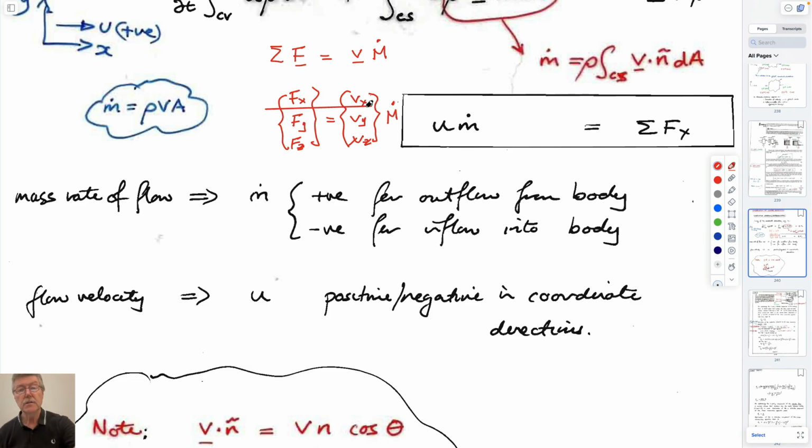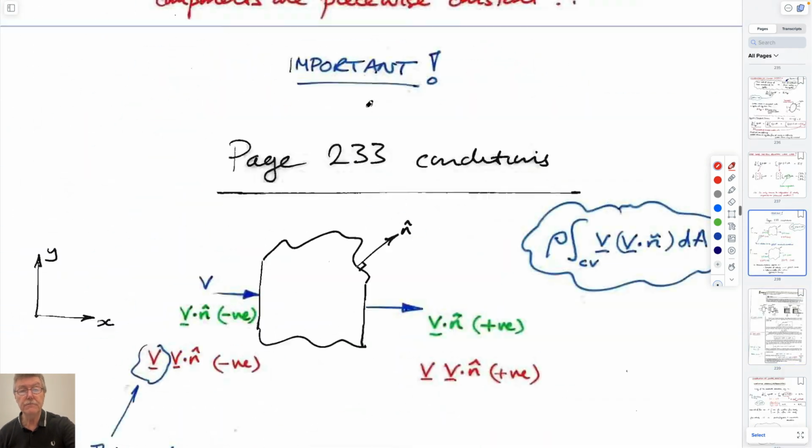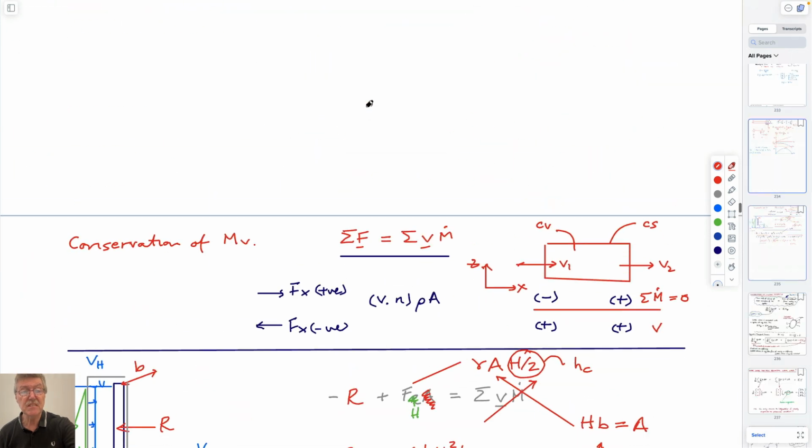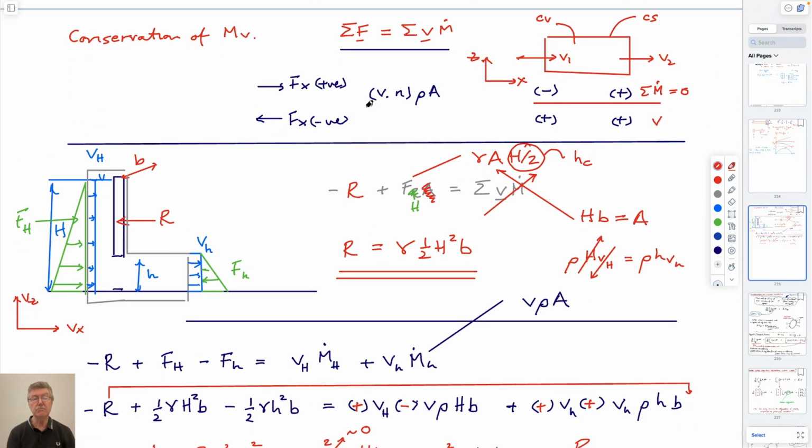We only need one equation. We could also solve for forces vertically if we wanted to. I'm not sure what it would tell us, but we could do it in z, and we could do it in x. I think the sum of the forces in both z and x would be zero. No net forces, because if you took a box, this L-shaped box, and looked at the static pressure distributions on either side, they balance each other in the y direction.